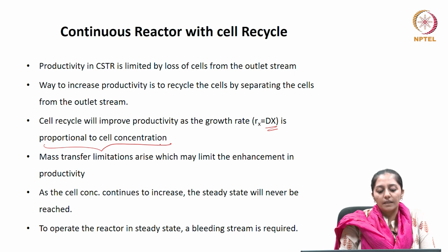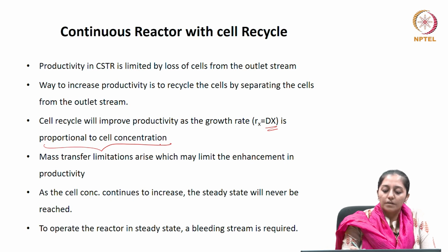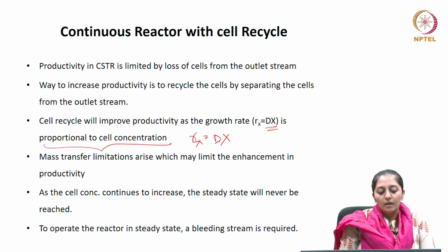So, cell recycle will improve productivity. Why? As the growth rate is proportional to the cell concentration. Rx is equal to D times x in a steady state CSTR.